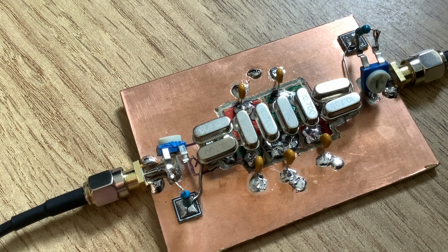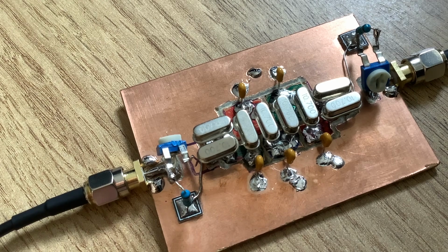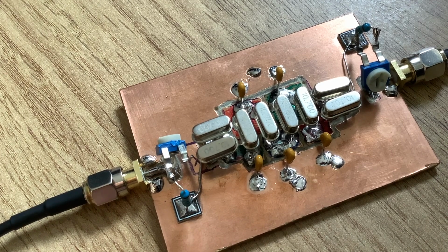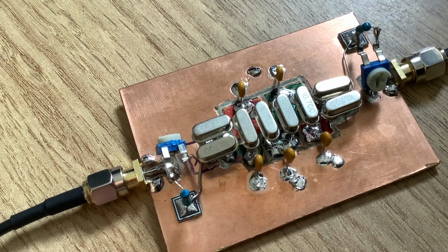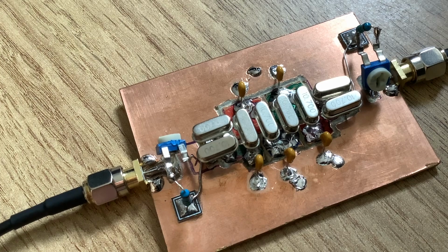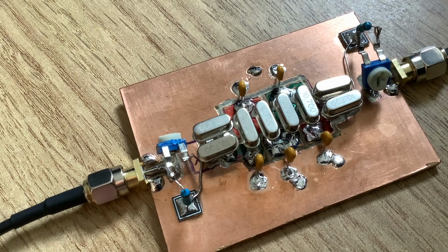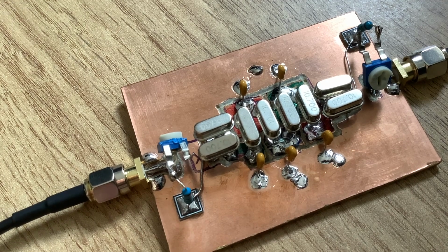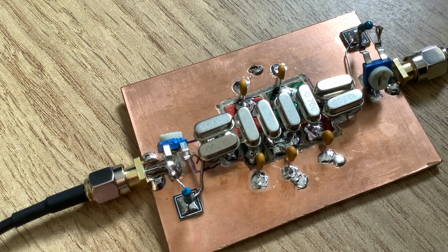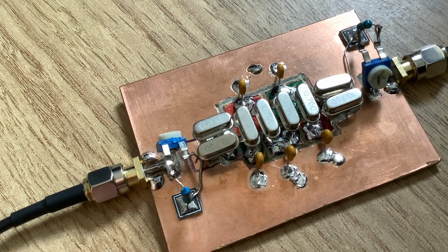This time I'm actually building a crystal filter for FM, for narrowband FM. And it may be narrowband, but it's still a lot wider than single sideband. So instead of aiming for a filter with a bandwidth of, say, 2.4 to 2.7 kilohertz, I'm looking here to do something really between, well, anything between 9 and 13, I suppose. So a lot wider. So I needed something wider. So I needed to go the other way. I need to go down.